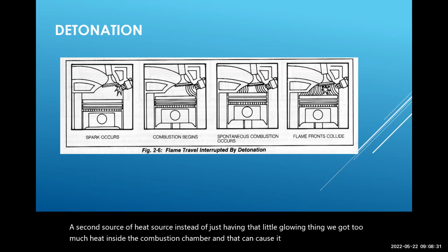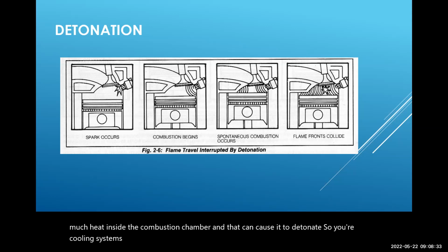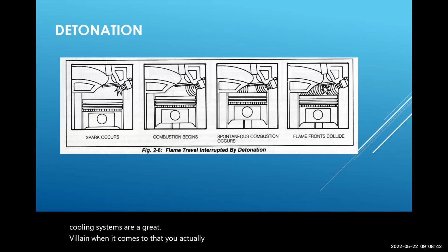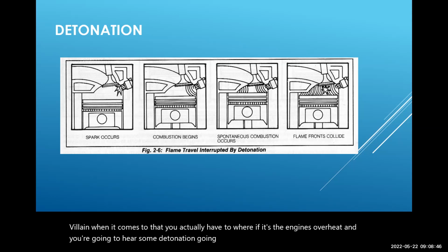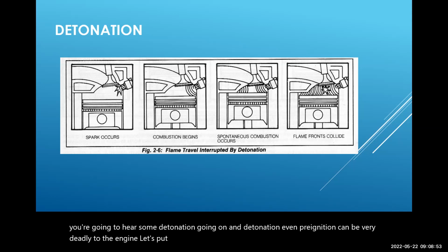So your cooling systems are a great villain when it comes to that. If the engine's overheating, you're going to hear some detonation going on. And detonation, even pre-ignition, can be very deadly to the engine. On top of that, it produces extra smog too.